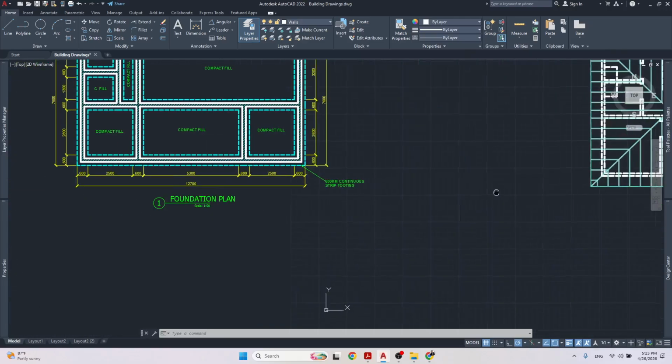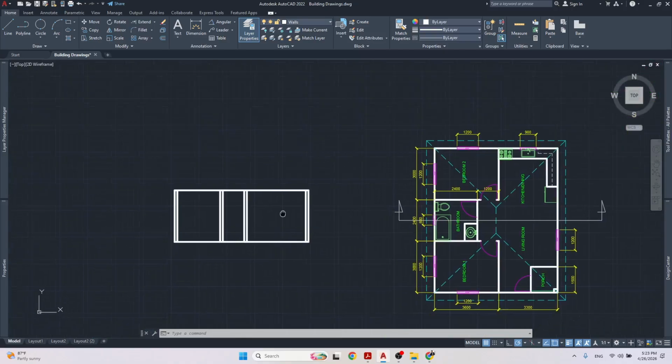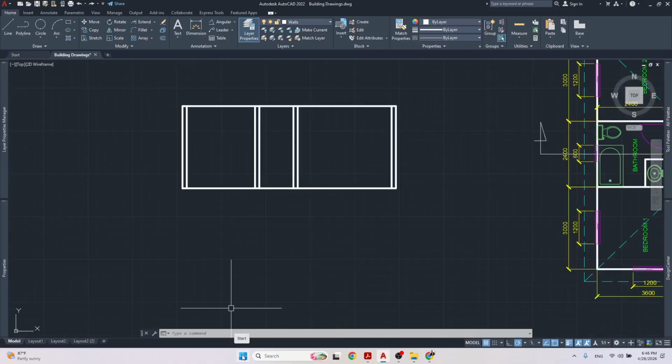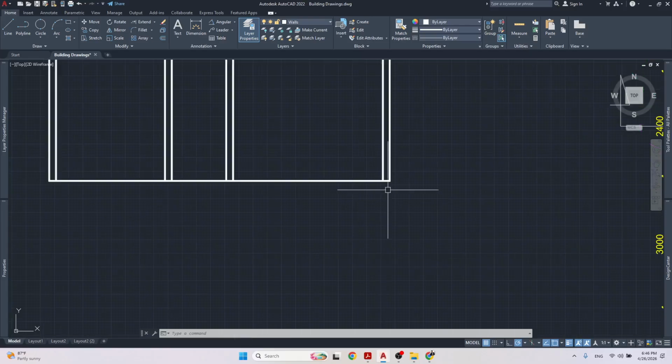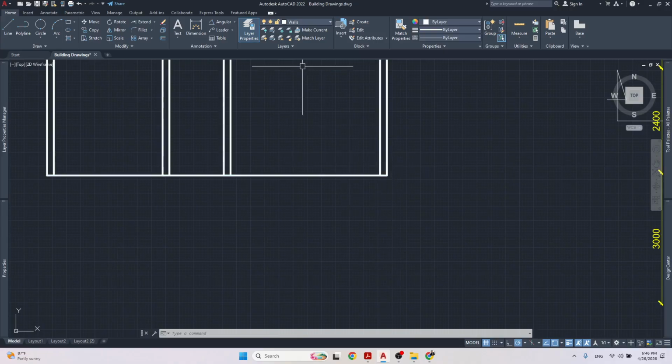All right, so let's head back over to the drawing over here and let's continue. Let's start with the foundation. First thing we're going to do now, CSEC might give you the details. They might tell you that the concrete slab is 4 inches. For the full section, do a 6-inch concrete slab. Let's do a 6-inch concrete slab, and that is going to include the finished floor and the sand blinding layer and the concrete slab itself.